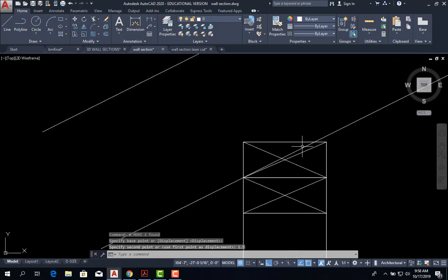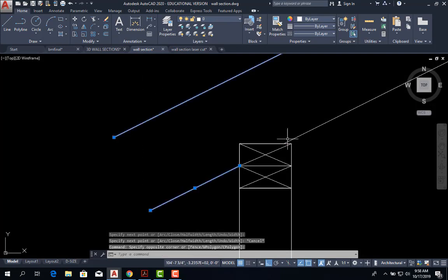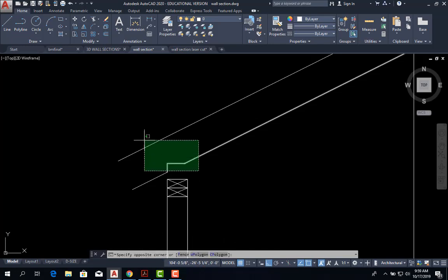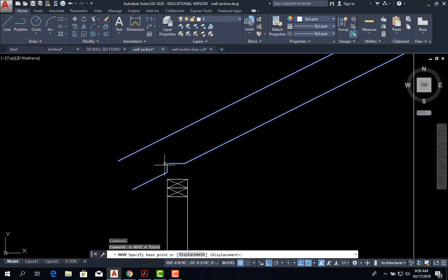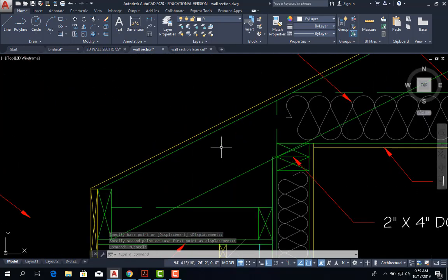So in reality what they're doing is cutting this member here like that. They cut that part, they cut this part, so it sits on it. Watch, let me pull it up. I'm going to put this right there, that right there, and that right there. So in reality this is a 2x6, and they cut it so that when they set it on top of the top plate, it sits right on it like that. That's what you need to do, and that's what I have here.